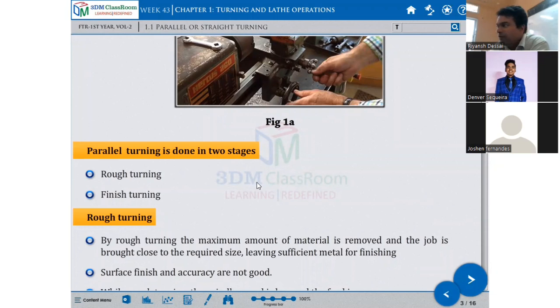While filing, when you measure the actual dimension, then you have to make it with a second cut file. Otherwise, if you take a bastard file at that time, there are chances of removing extra metal, and the dimension will go under. If it goes 1 mm under, what happens? You have to take care of that. While cutting, you always note where you have reached.